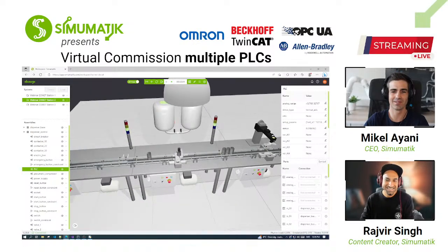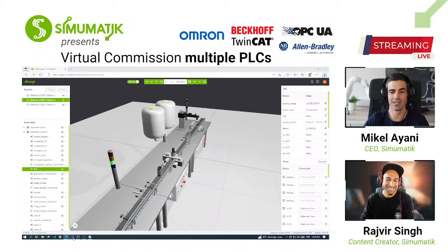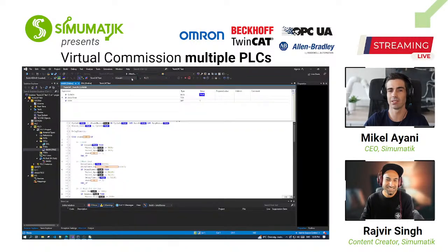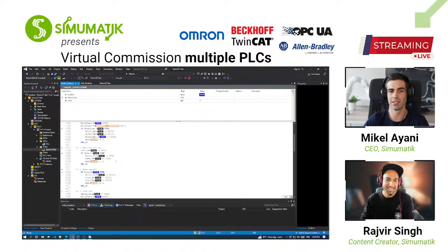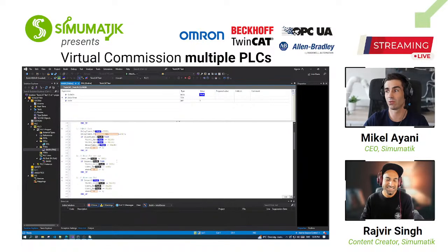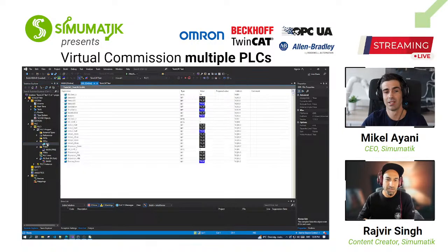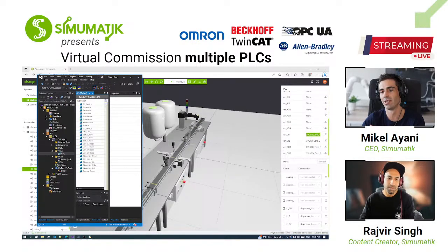So that was station 2 running TwinCAT, and as you saw, now in this explanation, why GBL? Because you need to send the entire path. GBL.dicar1 is the path you need in Simumatik. If you just write dicar1, it won't find it with ADS.